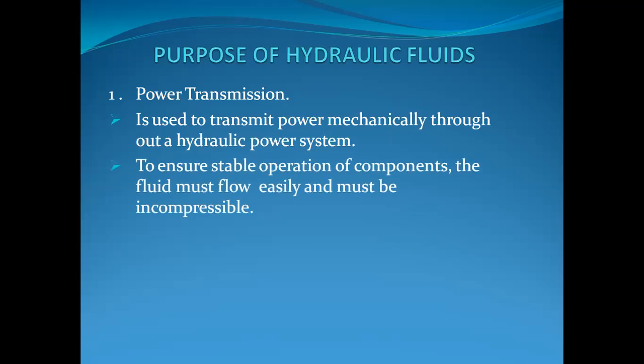To ensure stable operation of components, the fluid must flow easily and must be incompressible. That means the fluid is stored in the collecting tank, which is used to move some load on the other side, on the outer side. Therefore, the fluid stored in the tank is sucked by the pump and transmitted to the different areas through pipes. And finally, it is used for doing some work. That is, the pressure energy is transformed into mechanical energy.